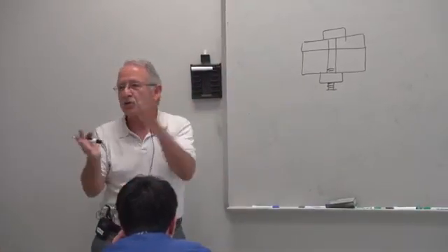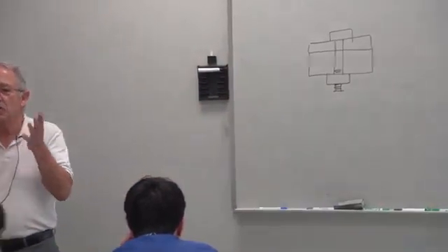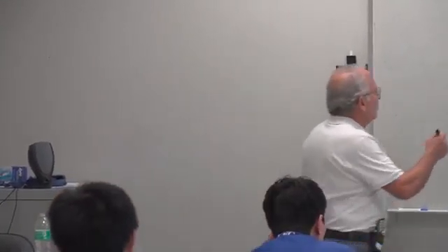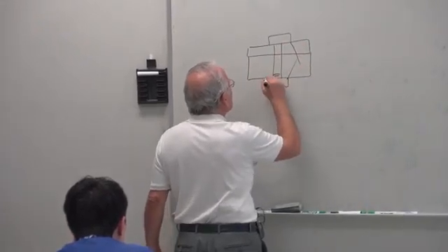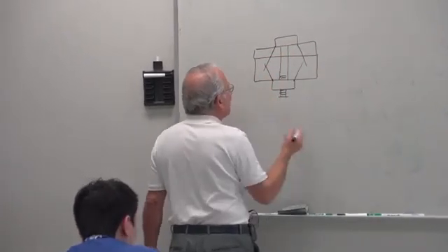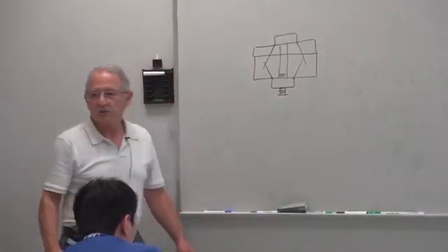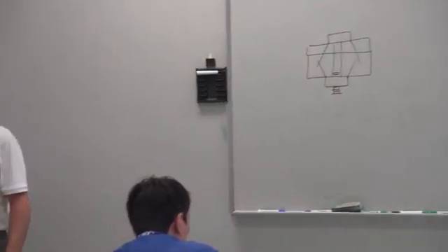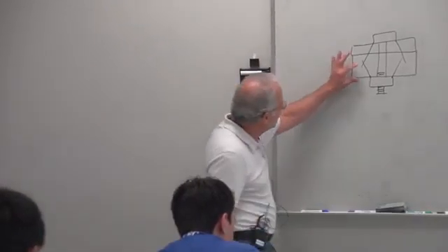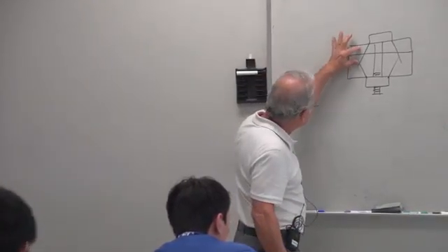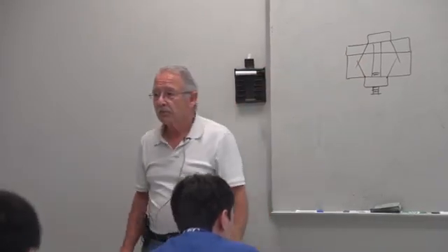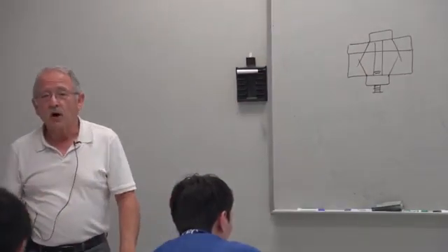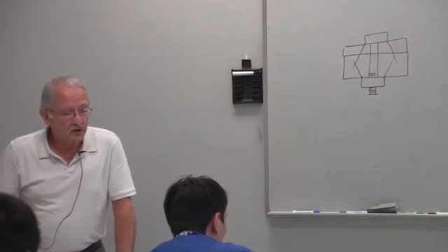All it sees is just steel in between. It's as though you had just one piece of steel and a bolt through that. So force diagram will look like this. But now you don't have to calculate 3 frustums because they're all the same. All you need to do is calculate it for this frustum and calculate it for that frustum. You don't even need to do that because they're exactly the same. So you calculate it for one and then find the stiffness.